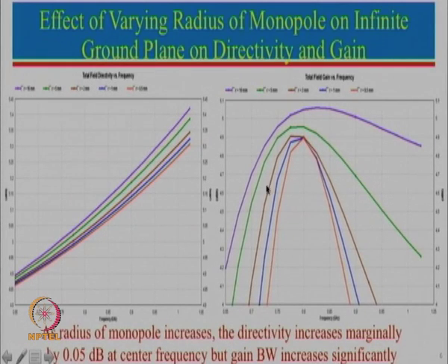But this is the plot of the gain. Now, the gain is what? Gain is efficiency multiplied by directivity. Now the efficiency of the antenna is still pretty good because it is using simple metal. So the metallic losses are very small, and dielectric losses are not there. However, what you see over here also accounts for VSWR variation over the frequency. If VSWR varies a lot, that means the reflection coefficient will vary, and that means effective gain. So the gain shown here is not accounting only for efficiency, but also for the reflected power.